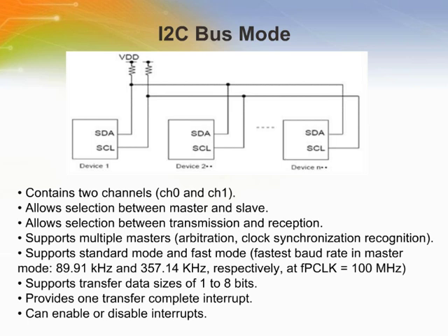The device that operates as a receiver can output an acknowledge signal after reception of serial data, and the device that operates as a transmitter can receive that acknowledge signal, regardless of whether the device is a master or a slave. The master device can output a clock for the acknowledge signal.